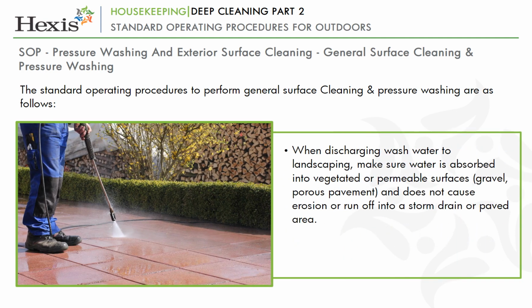When discharging wash water to landscaping, make sure water is absorbed into vegetated or permeable surfaces, that is gravel, porous pavement, and does not cause erosion or run off into a storm drain or paved area. All other wash water must be captured for proper disposal.